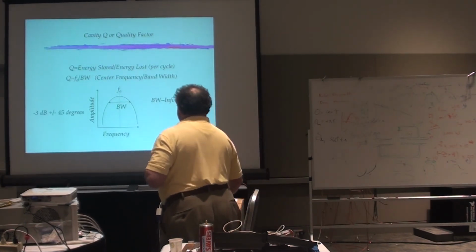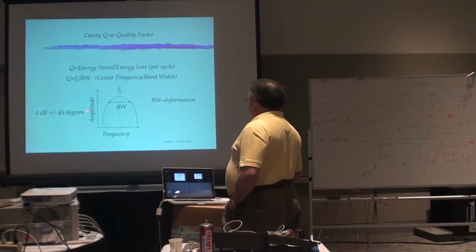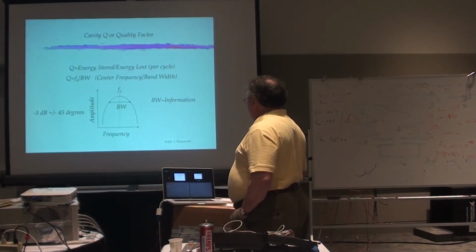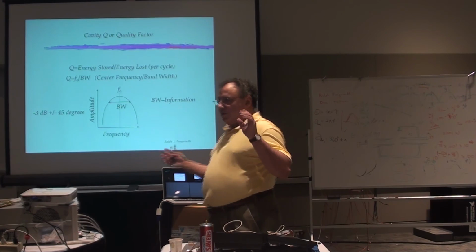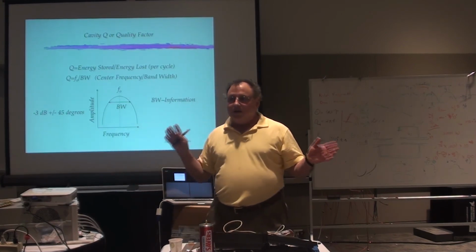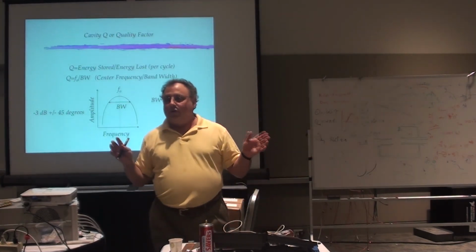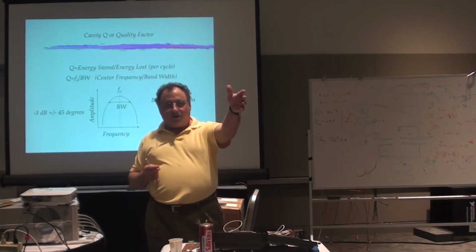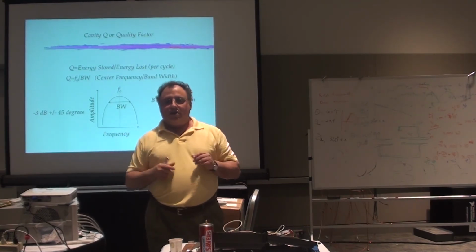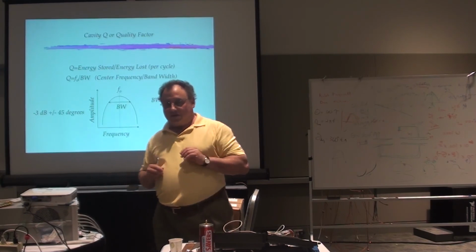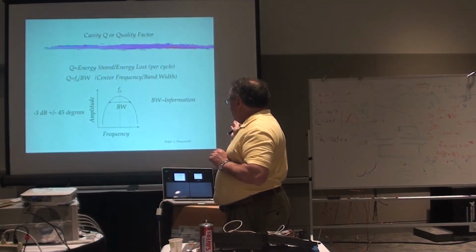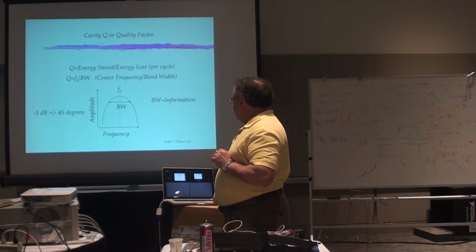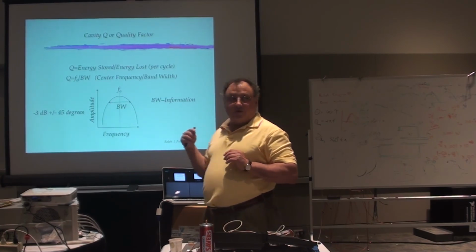I hope. Okay, an easy thing to understand, of course, is at the 45-degree point where the real and imaginary parts are equal, and that's the 45-degree point in the system. That's equal to the 3 dB point. This is how you're going to be measuring the Q0 on these cavities. Under those conditions, that will tell you what the bandwidth of the cavity is.